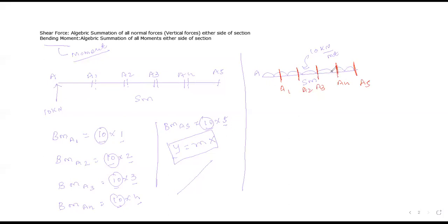So now again same procedure. Shear force at A1, I consider from the left side. Again, to calculate shear force of UDL, we need to consider the total load or point load of the UDL. In how much portion does it act in our case? Just check here. What was the length of A1? 1 meter. So can I say that a point load of 10 into 1 will act? Yes or no? Please confirm in chat box.